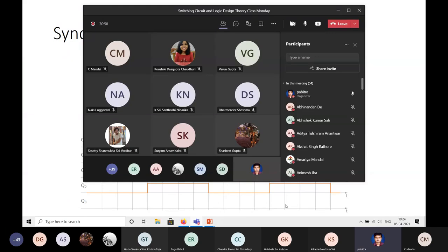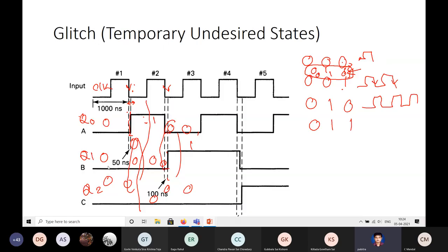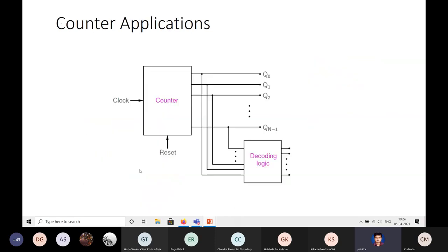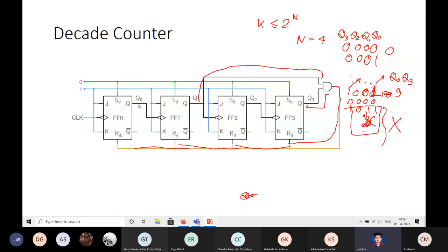Okay, so see, CRM is having another Viva. He will come back. Let me quickly cover one small part we did not cover in the last discussion about counters. We talked about asynchronous counters, where you have a ripple kind of counter where the output of a flip-flop goes as the clock of the next flip-flop, and it triggers on the downgoing edge.